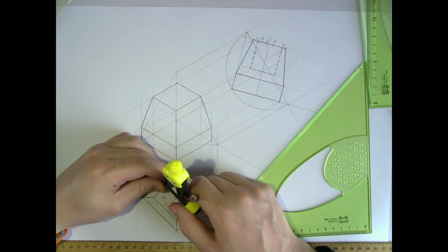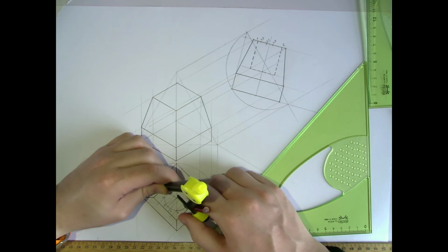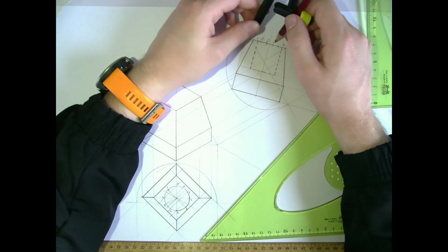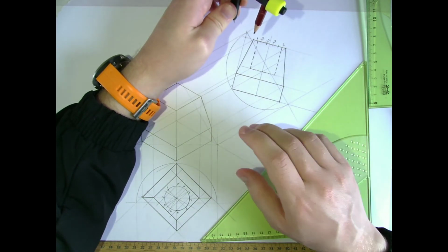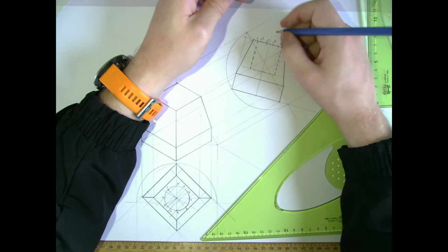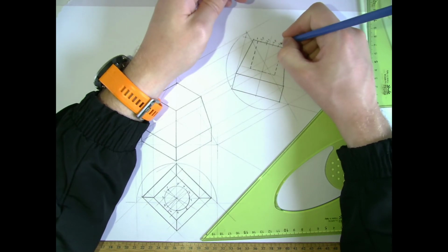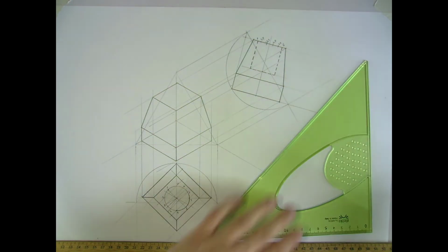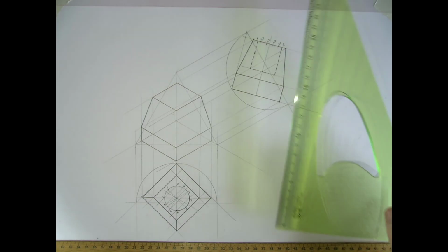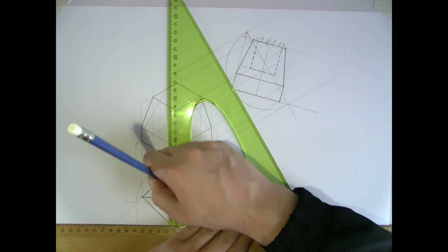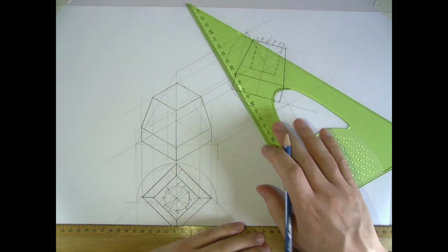So this is the final one that I need to measure. That's from 1 to 5, 7. You can measure it going the opposite way if you like. It doesn't matter. It's just so that you have a known point that you can measure all these points from. So the rest of this now is the same as every other piece that we've done with this. So we're just moving a point, projecting a point up into the axonometric view.